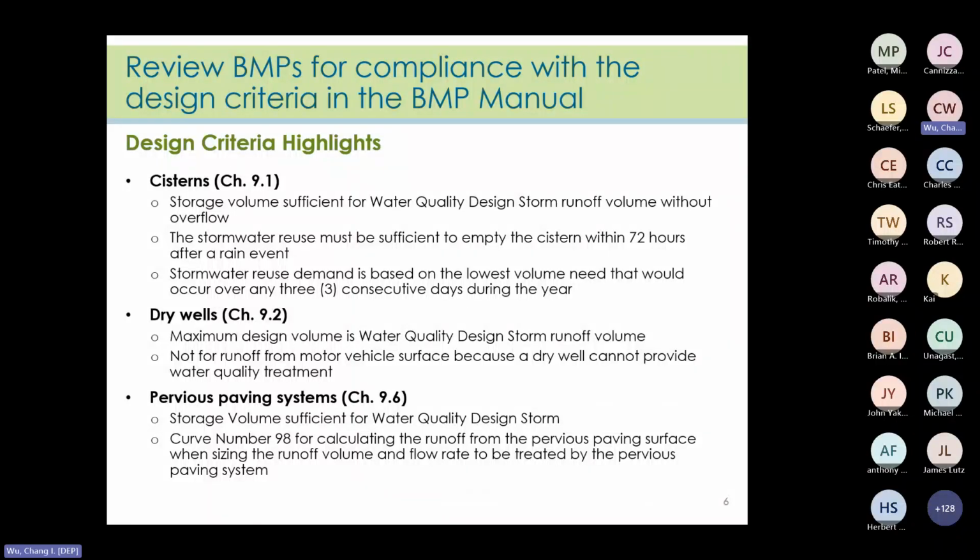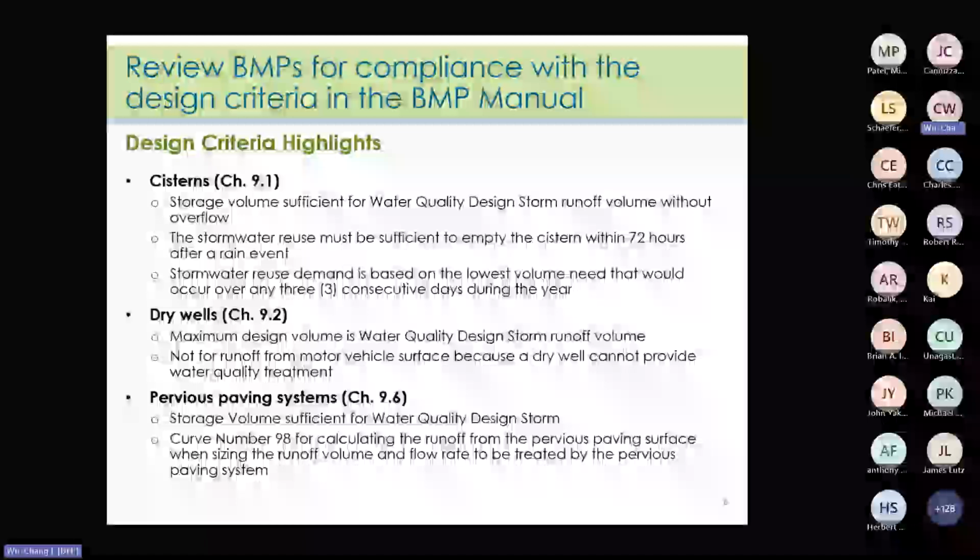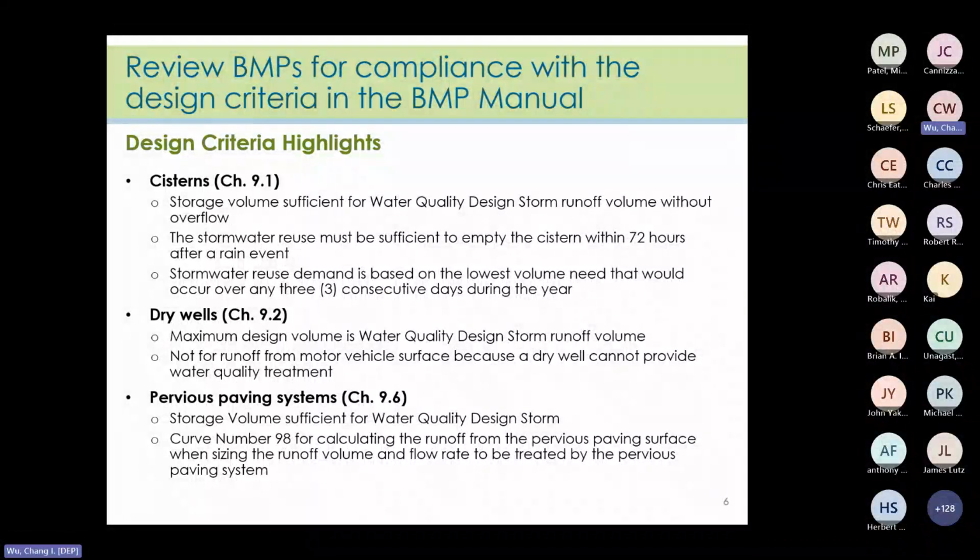Also, in the calculation of runoff on the pervious paving system, although there is no surface runoff out of the system, because most pervious paving systems are designed to take the runoff into the storage area, you need to use CN 98, so the amount of rain falling on the pervious surface can be calculated for the storage volume.